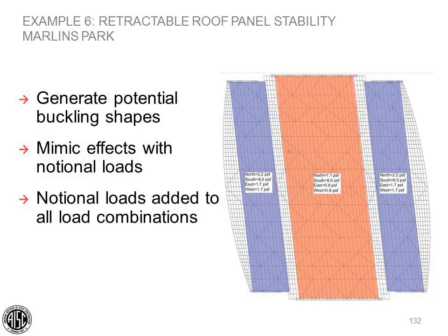We found it typically easier to apply the notional loads than to apply various sets of starting geometries. For instance, in the frames I showed, you would need to look at displacements in each direction combined with other loads, say lateral loads in each direction as well. So typically it's easier, at least in the software that we use, to use the notional loads instead, but certainly applying displacements is an option.